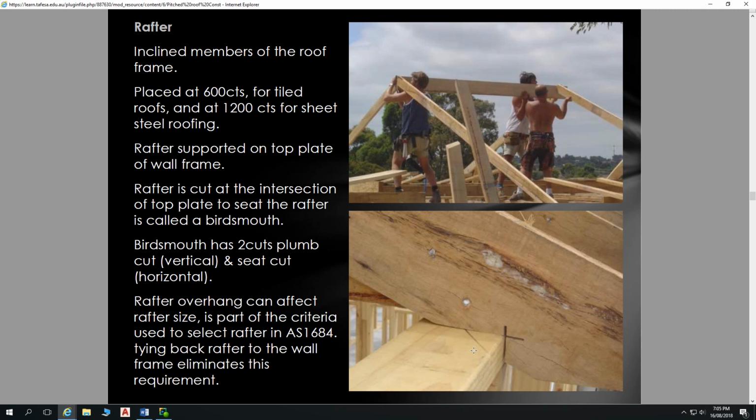These things do happen. That's where you don't have adequate tie down in sections. So quite often, if things get ripped off, typically from what I've seen, it's at this tie down here. It's inadequate tie downs between the roofing members and the wall frames.